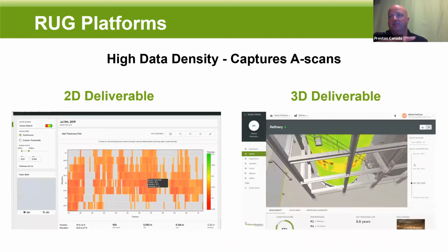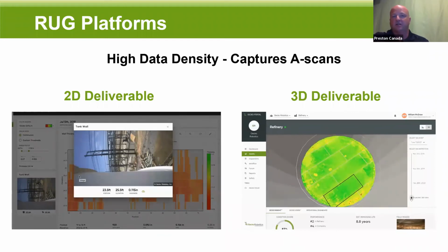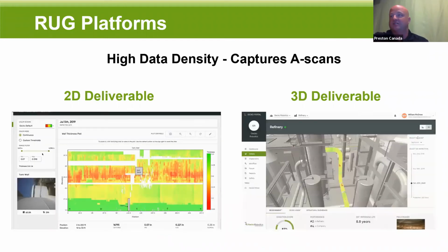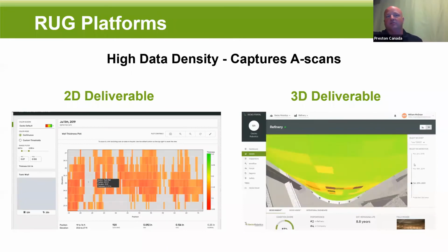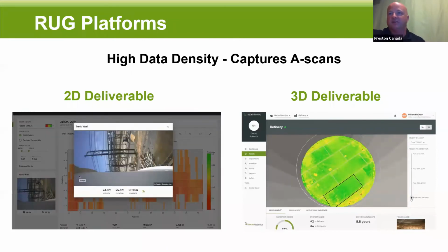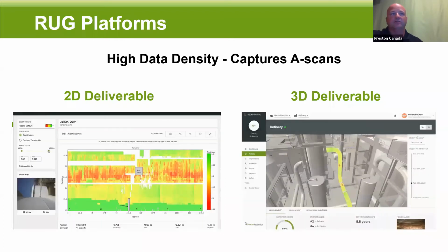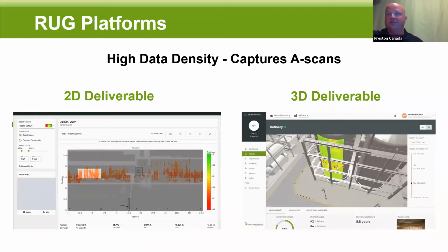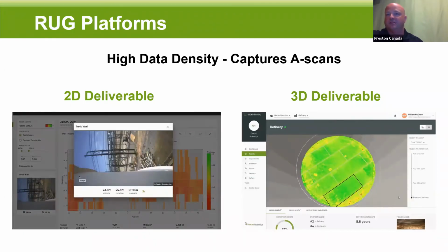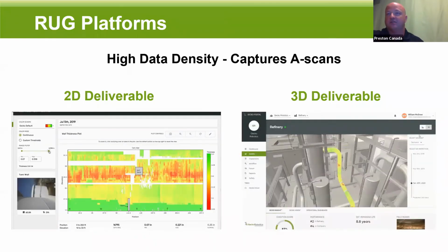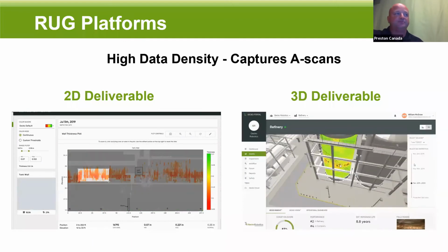And if the tank's a very large tank, at that point, we may just scan an area to make sure it's safe to stand on. But we never have to put anyone on the roof until we've done the safe inspection to see the condition of that roof. Worst case scenario, the robot falls through a very thin patch. And the 50-pound robot goes through, it's on a tether, we could pull it back out.